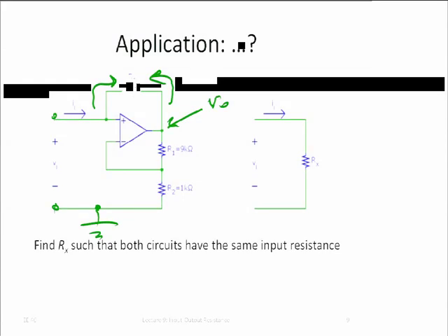The voltage at the output of an operational amplifier is simply the difference of the input voltages times the gain, which for an ideal op amp is infinite, which is the reason why at the input actually the voltage difference is 0 for an ideal operational amplifier with negative feedback.